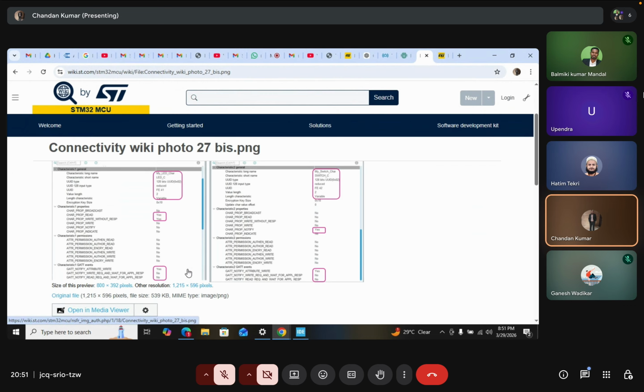Now tell me, what is the percentage that another person making this BLE device will be using the same controller that you are using, same two local names, same three UUIDs, same encapsulated values, along with the same characteristics. Okay, but my question is, we have created ABC 234 as a UUID example. So how do we get the encapsulated string of that UUID?